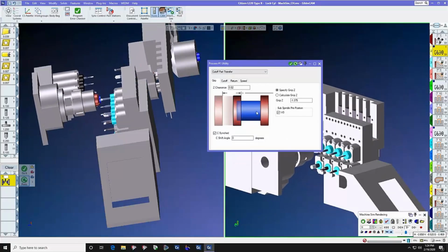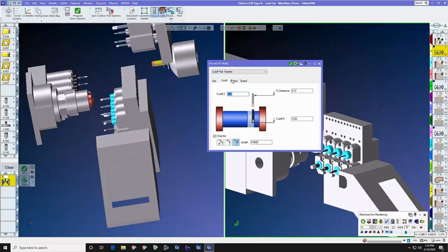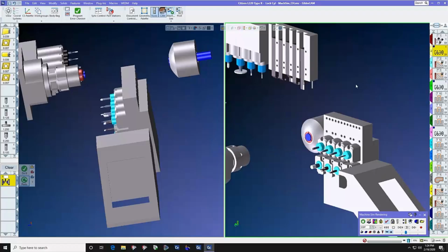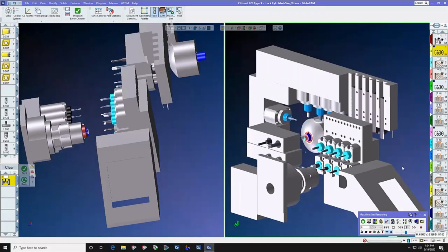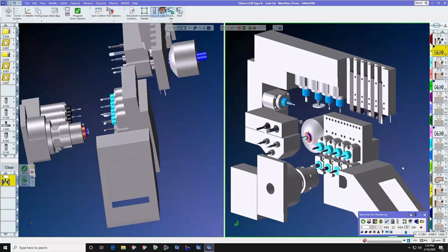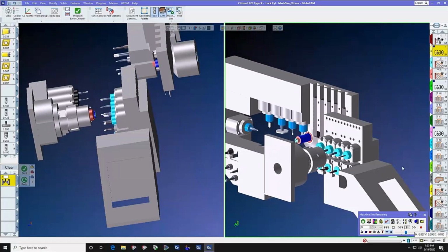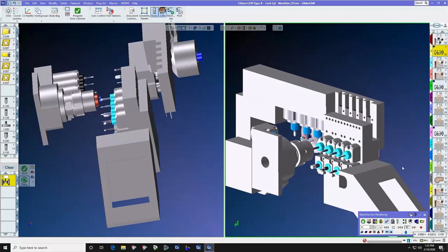It does the sub spindle in, it does the cutoff, we tell it where the cutoff Z is, the return, and the speeds and feeds at which we return. And that is a cutoff part transfer. Automatically, when we do a cutoff part transfer, you will see that the appropriate axes physically get out of the way so that the sub spindle can come in, the parting tool can do its job, and nobody has any collisions. Again, this is a function of MTM level 3.